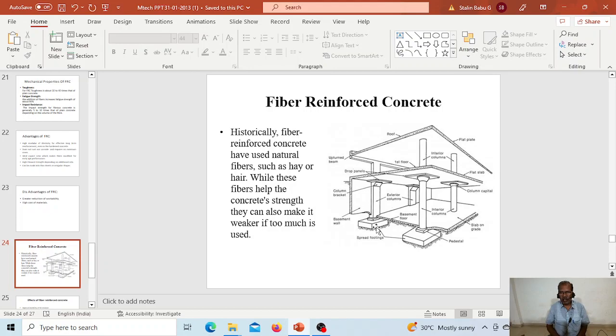Then you have to lay PCC and flooring, whatever the cost. Then you have to lay the slab. It has very good strength and there is no sinkage. That's why we are providing, as per the figure, fiberglass-reinforced concrete for the flooring.